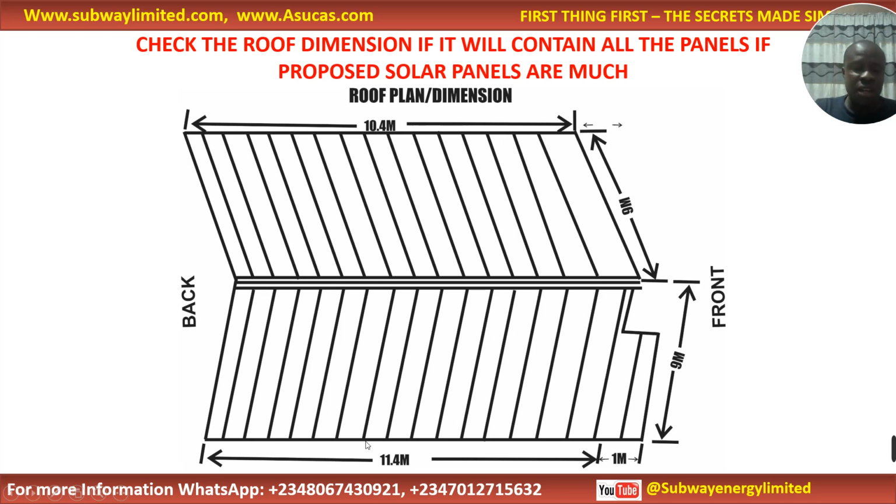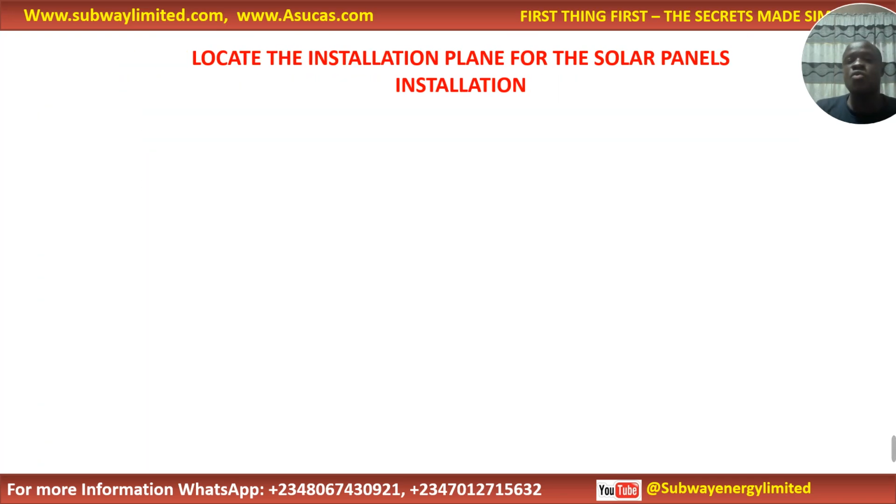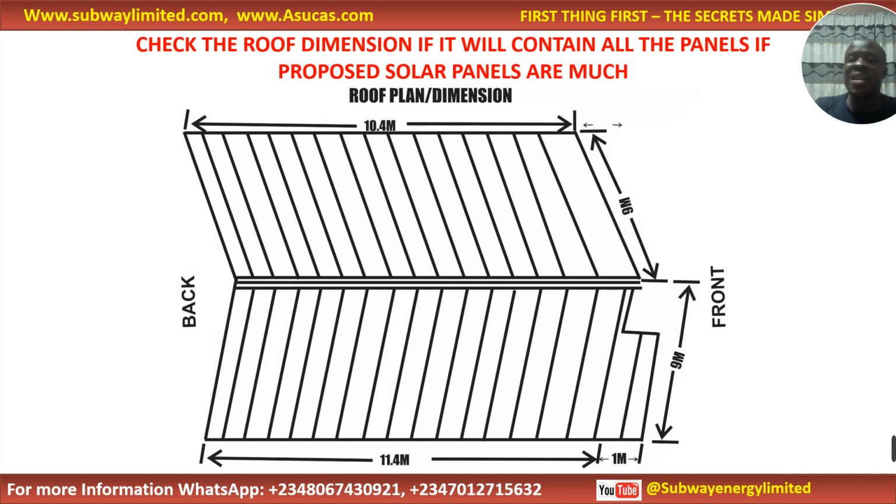This is the front, 11.4 meters, and this is exactly how this roof was. So you have to snap it, you have to go back and draw it, you have to put all the dimensions. It's not a small thing. So when you do your own, all these things will enable us understand exactly what we are doing. From here we will be able to understand how many solar panels would be mounted here, how we will arrange the panels and the rest.